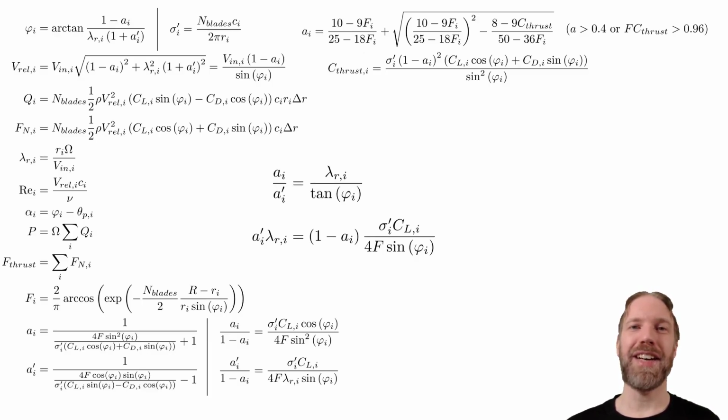This is actually the equation telling us that the induced velocity has a 90-degree angle with respect to the relative wind speed. This means that it's in the opposite direction of the lift force, which is exactly what we assumed when we talked about the tip vortices which induce the velocity opposite to the lift force. Hence, this expression confirms our earlier assumption about the relation between induction factors and tip vortices.